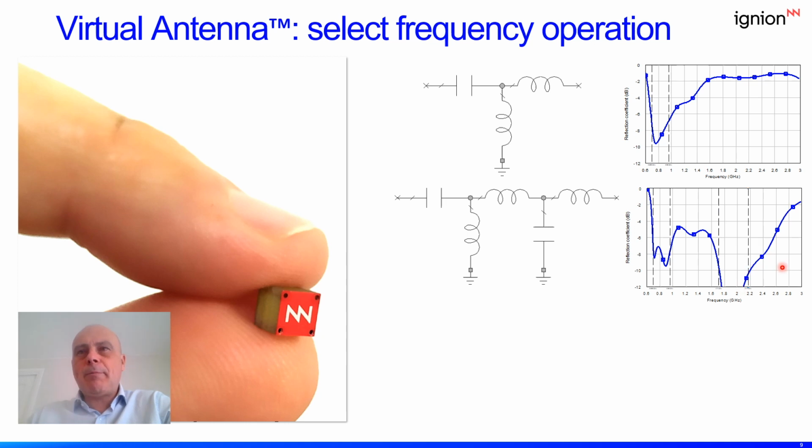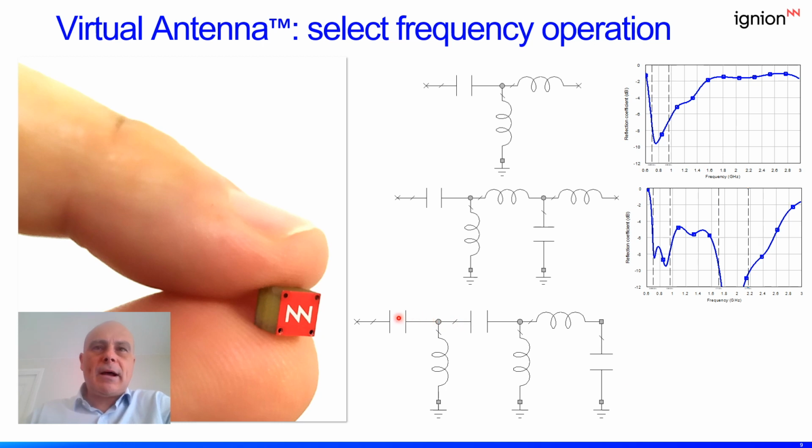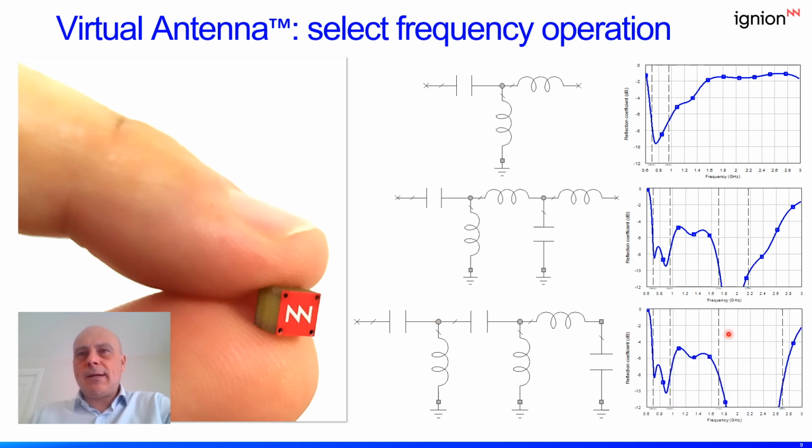And in case we want to expand the frequency bandwidth up to 10.7 gigas to include more frequency bands of the narrowband IoT LTE, then we can design a new matching network. As a result, you see that we can obtain this multi-band matching network. So designing wireless systems embedding virtual antenna relies not on shaping a new geometry on the antenna, but by just modifying a matching network. Besides being fast and simple, all these matching networks can be designed by software in automatic fashion.